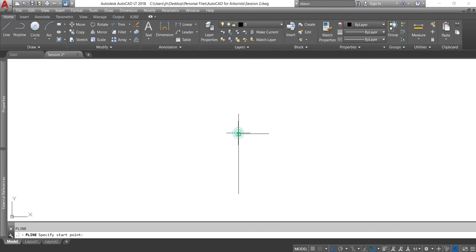And hit enter. So snap onto the start line again. Hit in the vague direction I want to go out on. And let's say that this is a 4 meter crown spread. I hit enter. That creates the line. Hit enter again and it completes the line.